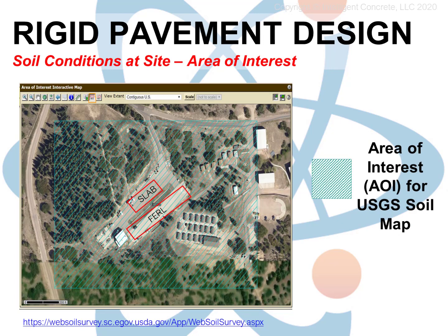The first step of the design process for anything that will rest on the ground is the soil investigation. This process is to determine the properties of the soil upon which we'll be building. For larger projects, we will normally perform a dedicated soil exploration, using drill rigs to obtain soil samples from below the surface and laboratory tests to determine the soil's engineering properties. However, sometimes that process is not available to us and we have to resort to other means.